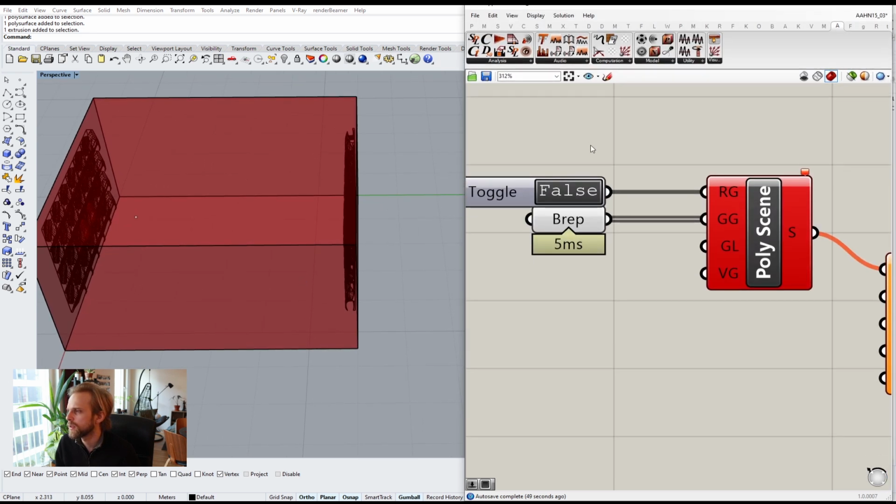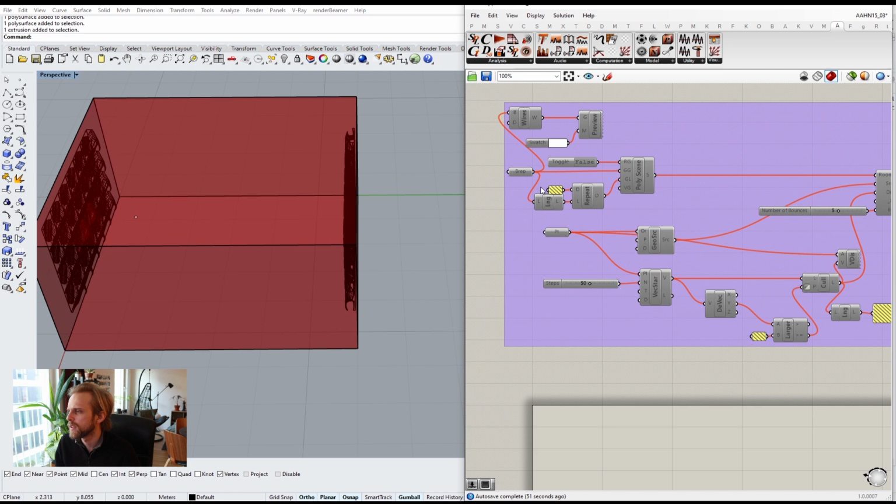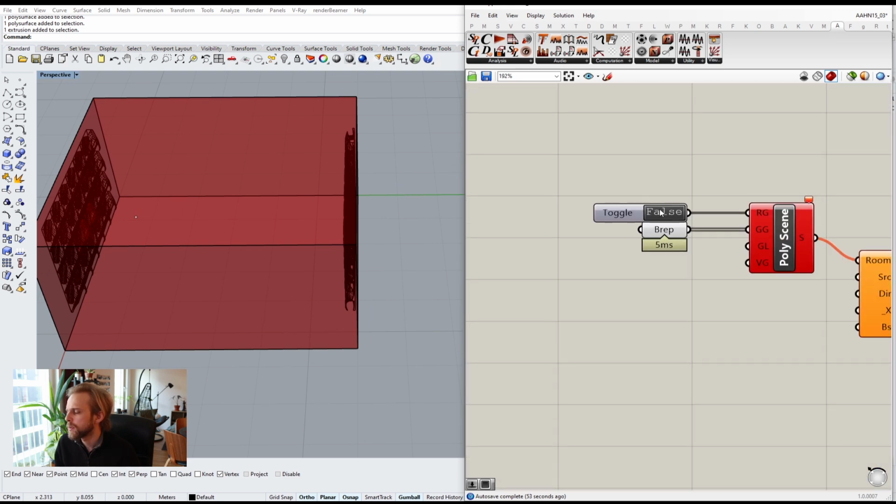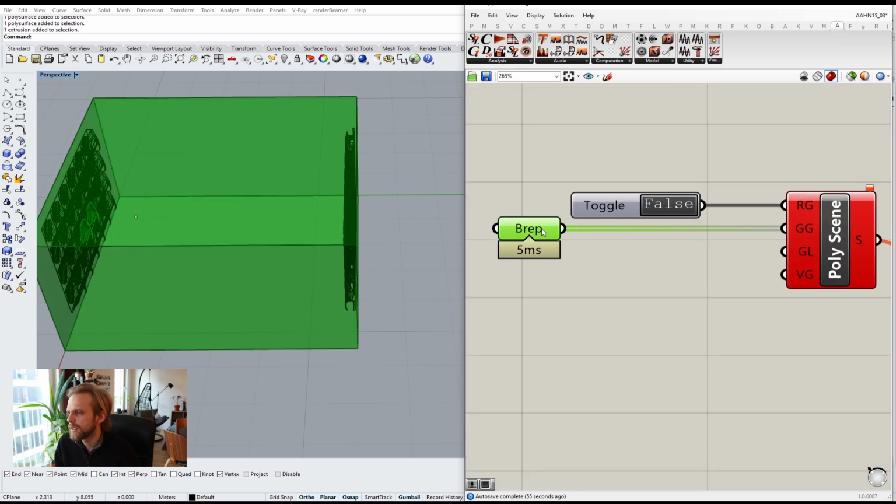So what we're going to do, and actually let me double check this. Yeah, what we're going to do is for every BREP that we have, we will set the index of the layer to 0. That's because I have only one layer, called default, and that is right at the top, so it means it's layer index 0, right?